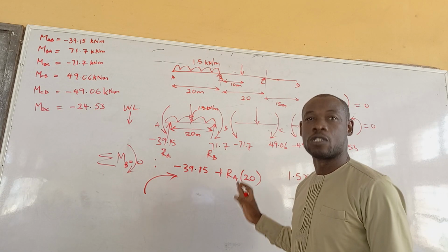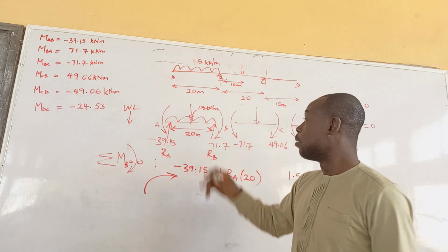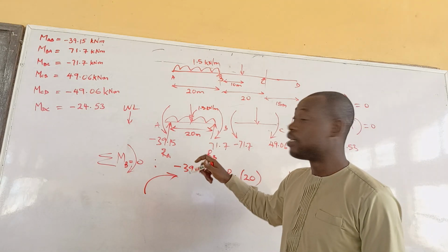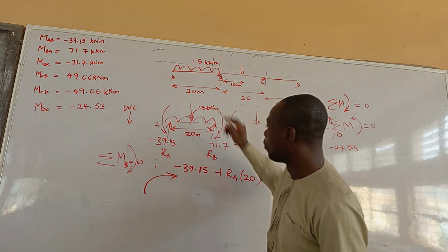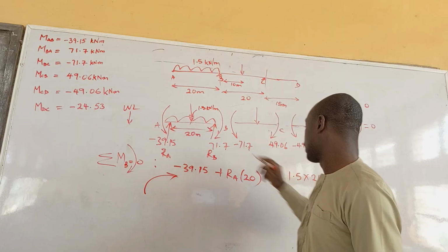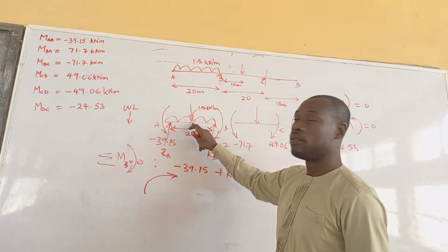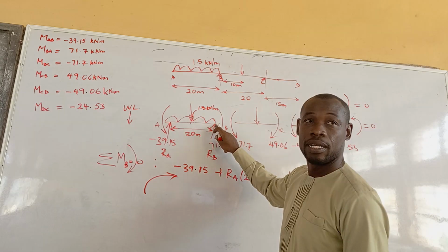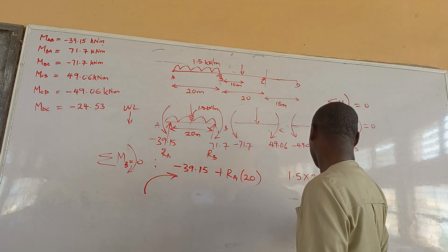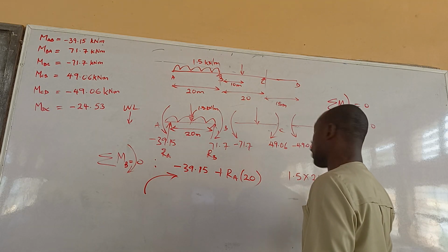Now, this is just a force, and we're looking for moment. Moment is force times perpendicular distance, right? This one is acting in this direction. What is the perpendicular distance? Distance from here to here? 10, right? Or 20 over 2, right? Yes. That's the one you know.